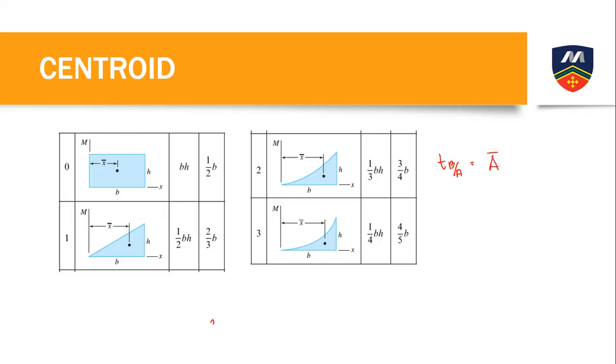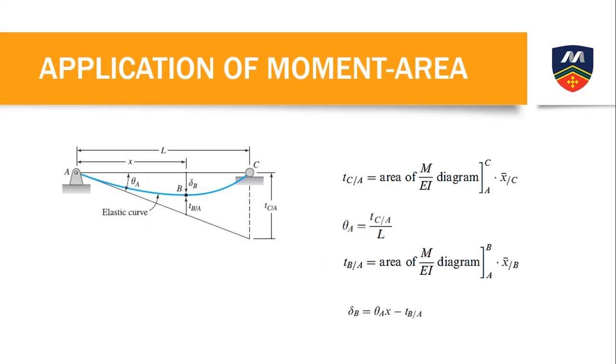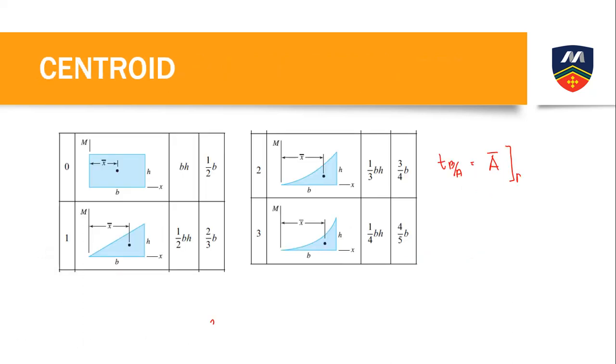What is the other symbol for area? From A to B, then the centroid, any centroid from B or relative to B. So our centroid here, is it different? Our centroid varies depending on the shape of our moment diagram. For the rectangle, the centroid is just 1/2, right? But for a triangle, it could be 2/3 or 1/3. But for parabolic, in this case, where is the centroid?